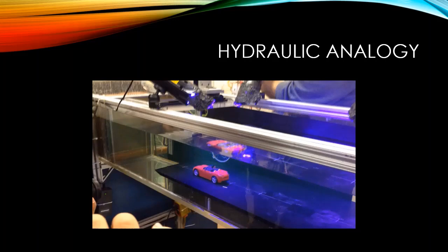So there are various disadvantages in high speed flows, but this hydraulic analogy will be useful for having a simple model in a simple manner. I can keep a small miniature model in a water flow tunnel, simulate it, and then compare it with the real model.